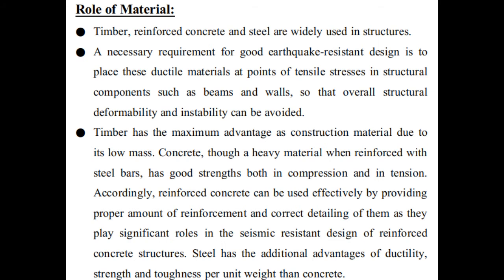The necessary requirement for a good earthquake resistant design is that you should place the ductile materials at the points of tensile stress in structural components such as beams and walls, so that overall structural deformability and instability can be avoided. Ductile materials are designed to take the tensile stress, so they should be placed in a proper place while designing. Positioning or the placing of the ductile materials is very important.